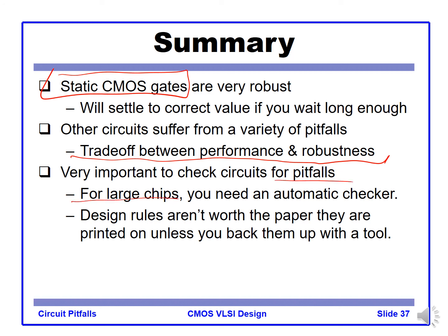For a large chip, you need an automatic checker or script that checks your design. Design rules are not worth the paper they are printed on unless you back them up with a tool. With a tool you can verify it. So don't rely too much on the design rules.